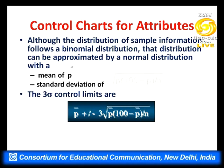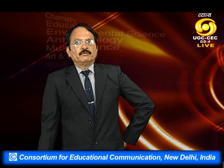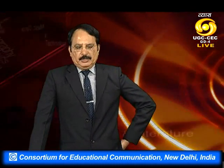The 3 sigma control limits are then p bar, which is the mean, plus or minus 3 times the square root of p into (100 minus p) divided by n. This will give us two limits for the control chart, and the control chart will be drawn with these two limits and a mean value. Mean value is given by p bar.